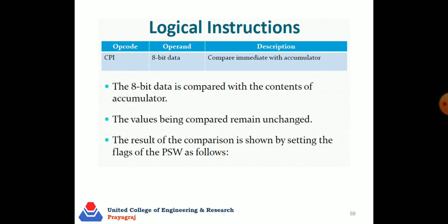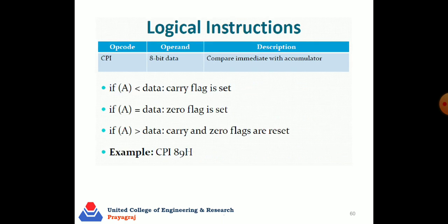It is similar to the previous case, only here we have 8-bit data. As in CPI, if A is less than the data, the carry flag is set. If A is equal to the data, the zero flag is set. If A is greater than the data, the carry and zero flags are reset.